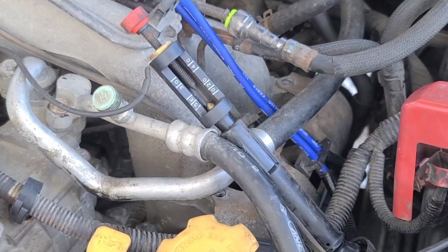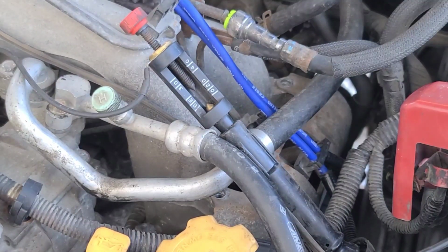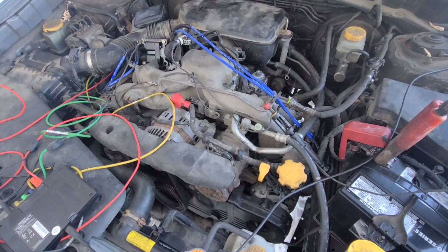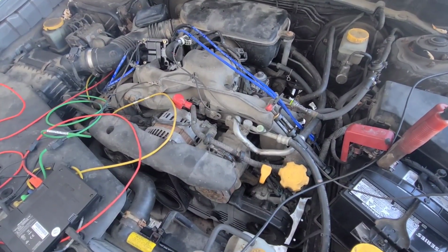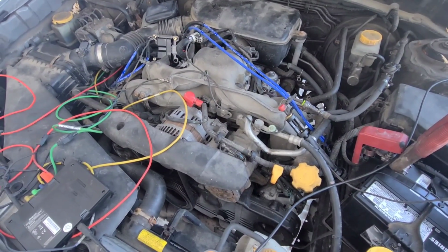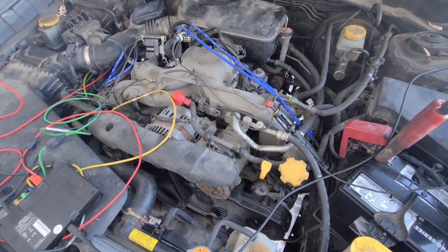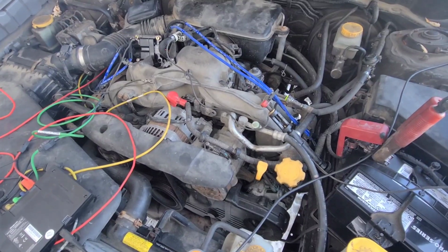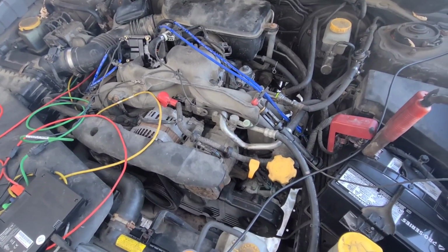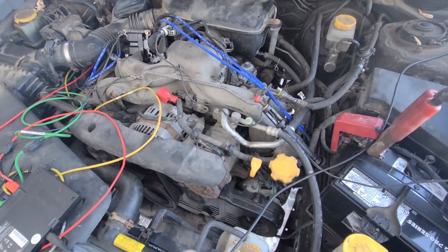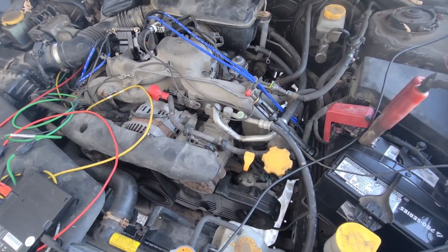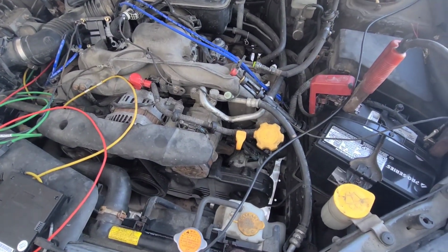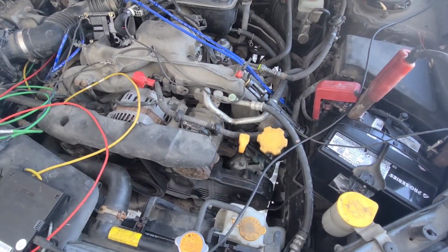I didn't hear any spark. Well, this car is eating my lunch. I got ignition coil control signal. I got injector pulse. Oh, I can hear the fuel pump running. But I got no spark. What's going on with this thing? This thing needs a priest.